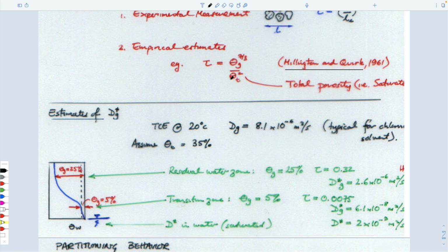So I guess this total volume here would be the porosity, right, if it's saturated. So phi T is equal to the volumetric moisture content of water plus the volumetric gaseous content. The sum of these adds up to the total void content.